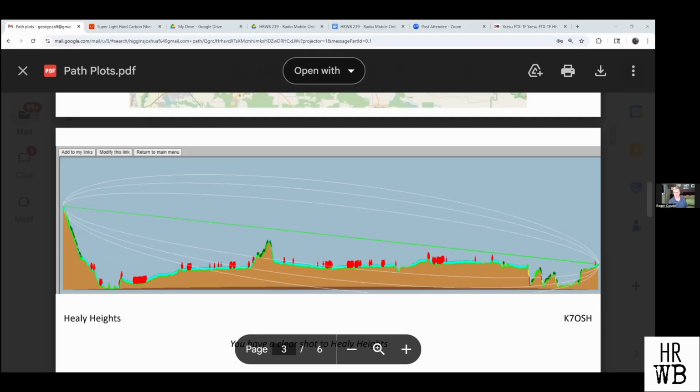You don't want that because you will lose communication. This is typically happening if you have a radio path above the water. You will lose signal two times a day, when the sun sets and at sunrise. So this is really interesting.